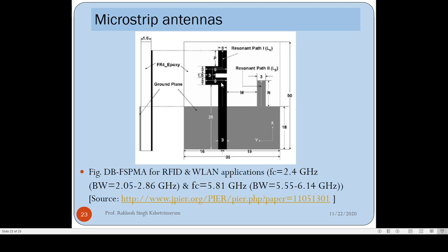This is a feed line. This is the structure of the patch. We have folded the antenna, so that is a folded monopole antenna. Monopole antenna because we have removed the ground plane here. People usually call this kind of antenna a monopole antenna. This is no longer a microstrip antenna. This is a printed monopole antenna, which is a variant of microstrip antenna with a partial ground plane. So we have a folded structure here.